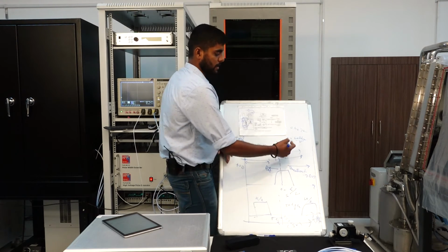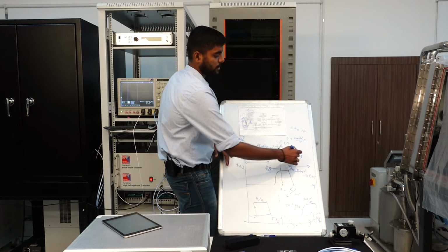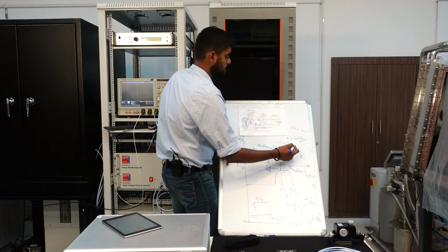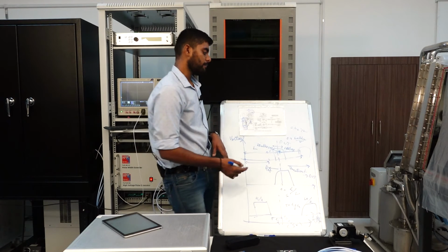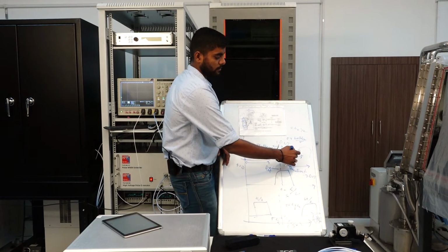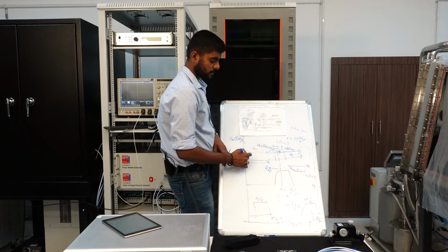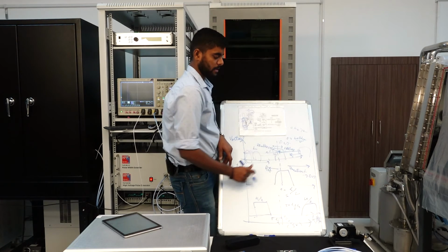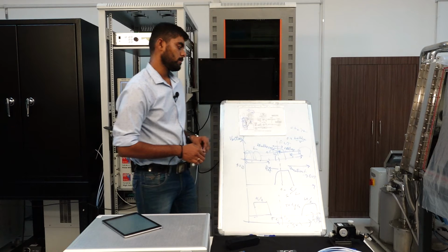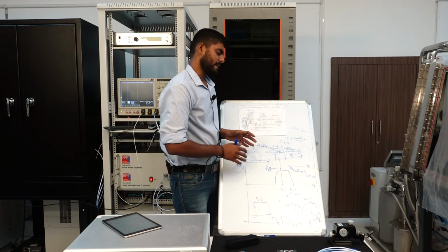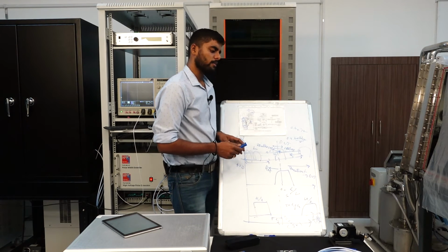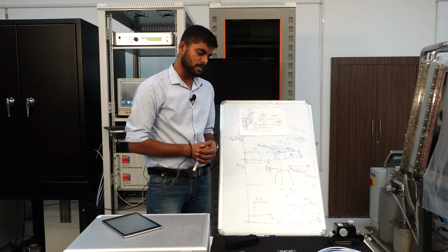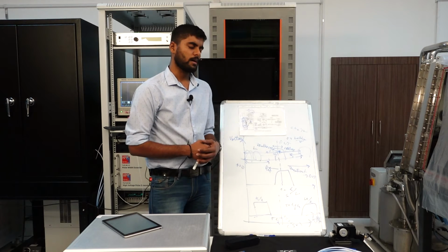So for example, if the time period from the DUT to the switch and back is more than 100 nanoseconds, say it's 1000 nanoseconds, then by the time the DUT reflects the signal back to the switch, more incident waves would have been generated, and they would interfere with the whole measurement setup. So you would like to optimize these lengths so that you have a lot of flexibility in the time periods you can use. So this is an important physical understanding to have regarding the TLP setup.